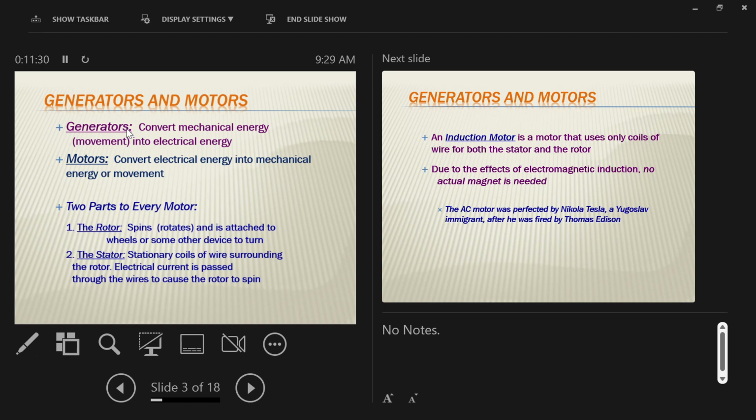Okay, so basically power stops going to the wheels, right? And the wheels continue to turn because the weight of the car is pushing the car along, right? And the power will be fed back through the motor because the wheels are now turning the motor, okay? And power goes back to the battery. So when you brake on these regenerative braking electric cars, you are putting power back in the motor. What would have been waste heat, just wasted out into the environment, is now put back into your battery, and then you can use that to propel you down the road.